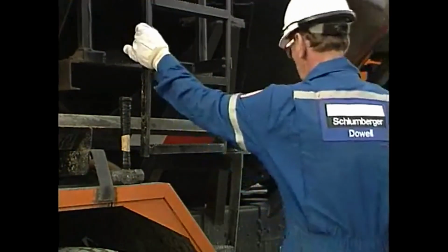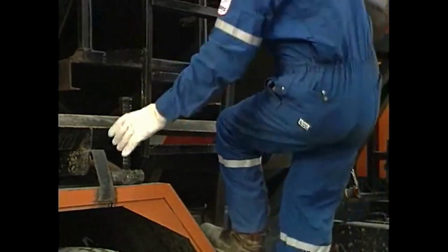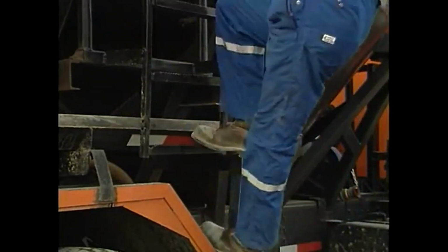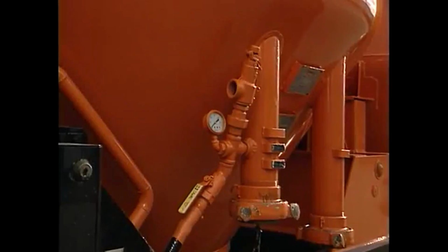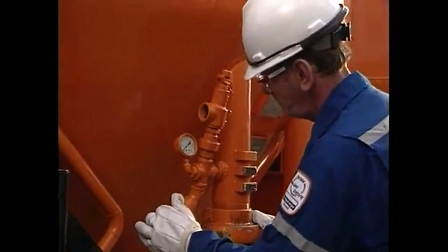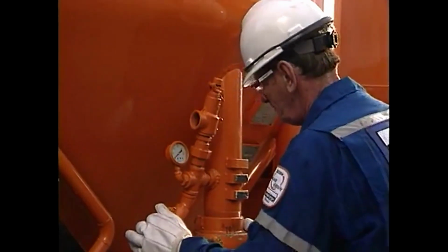Frequently, the victim was trying to correct a leak by hammering on the hatch or opening a hatch on a vessel that still contained pressure. Always respect air pressure. Never assume anything. Don't assume the pressure gauge works. Don't assume the relief line is open and unobstructed.